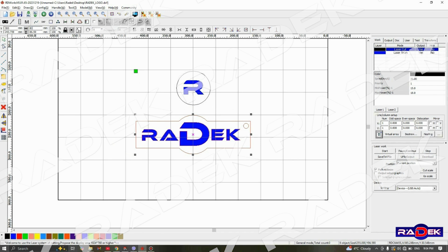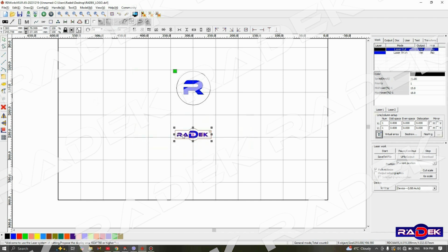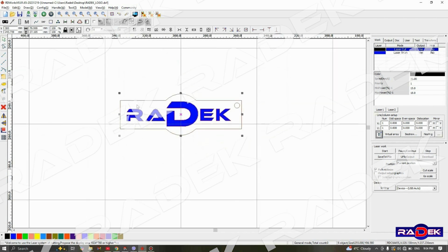Now the design has changed its size proportionally. Decreasing the width resulted in a proportional decrease in its height. We can also change the vector's dimensions by percentage, and we can do this by changing the value in the adjacent fields. I'll increase the width by 5% and I'll enter 105% in the designated field.